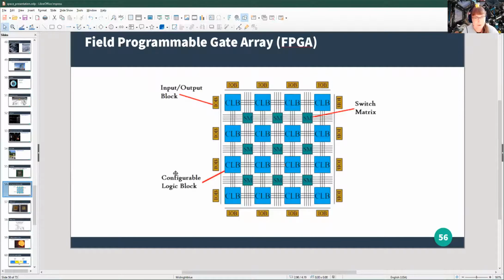Essentially the way they work is that you have a bunch of inputs connected to what are called configurable logic blocks. Each configurable logic block comes with something like a logic table and some flip-flops, and you just program each one, and you can use that to create gates and connect the gates together. Pretty soon, if you have enough of these CLBs, you can make your own custom microprocessor. And oh my God, that is so cool. You absolutely need these in space because, like I said, one goes up 16 and one goes up 17. You're not making a mass production run of these.